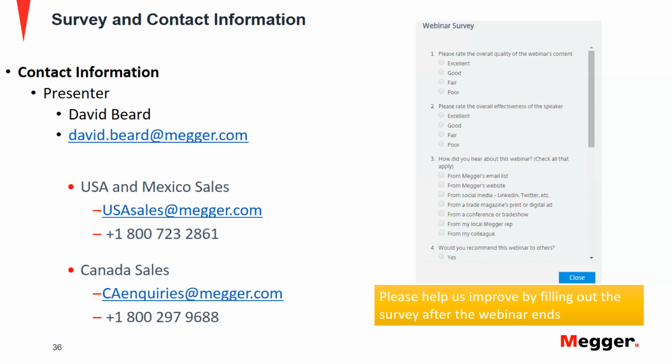We do have a meter function inside RTMS as well. It allows us to put in a current, voltage, and some angle on each individual phase, and then it'll go through and calculate whether the applied values compared to the measured values are correct or not. That gives us a quick wiring check. I hope that's answering the question correctly. If not, again, leave us some information. We have email, we have the survey. That way we can better answer the question as well. But hopefully that gave you an overall idea.